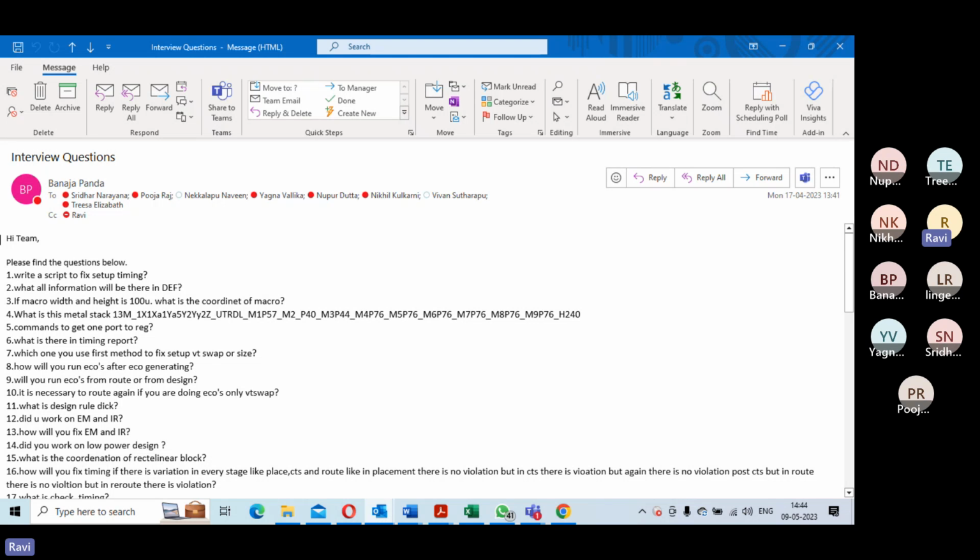The second part of your report segregation is to take all the paths reported all the way up to 0 picosecond, and collect all the cells whose delays are, let's say, more than 200 picosecond or 100 picosecond. Typically in a 7 nanometer technology, the cell delay is supposed to be like 20 picosecond. So an 8 picosecond or 5 picosecond buffer, and if it's a 2 input AND gate, it will be in that single digit.